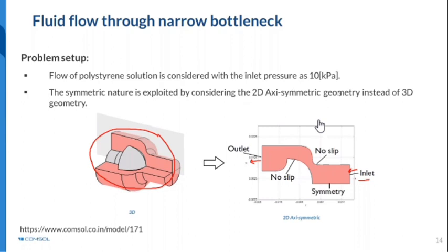So one person asked me that delta x has to be less than or equal to that. The minimum element size has to be lambda by 5. You can further reduce element size, you will get better results, of course. But you cannot go for an element size which is higher than lambda by 5. So for example, if lambda by 5 gives a size of let's say 0.1 meter, you cannot go for 0.2 meters. You have to go for either 0.1 or 0.09, less than that size.